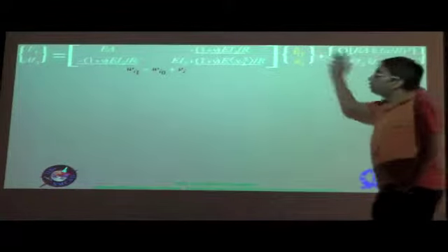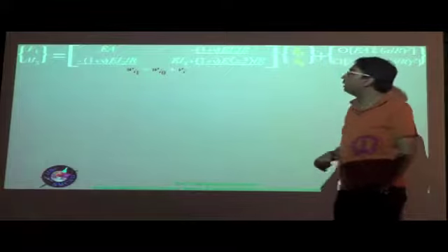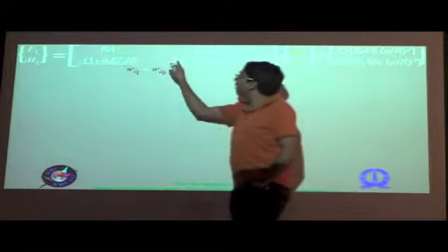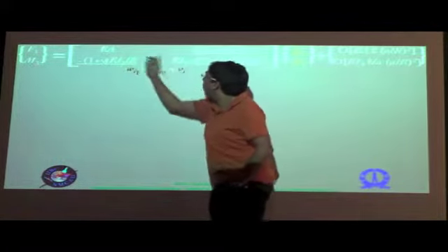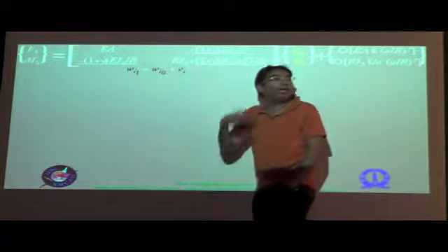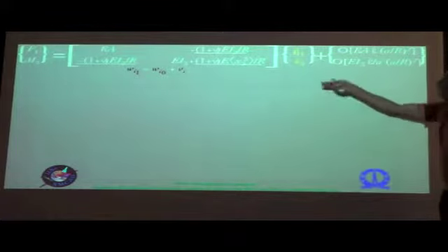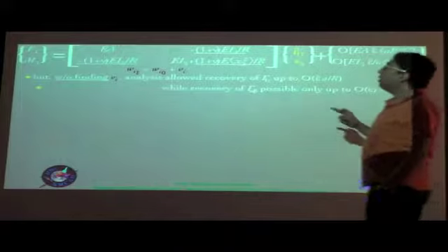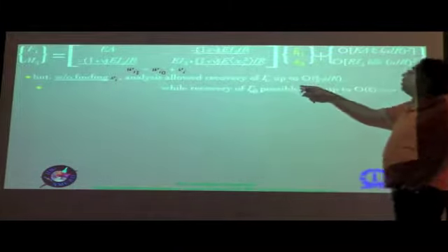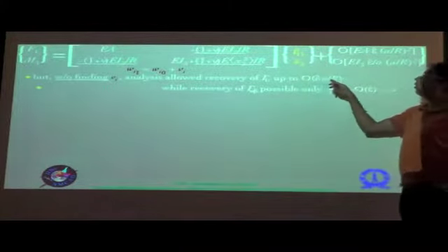So this is of course the constitutive law that we got in the previous example, the isotropic example, and we said that the non-underlined terms were the zeroth order approximation, the underlined terms were the additions that we got with the first order approximation. And of course, if you go to higher order approximation, the next correction, for example, would involve an A by R squared correction in both the axial force stress resultant as well as the bending moment stress resultant. But without finding VI, the analysis allowed the recovery of gamma 1i already up to order of epsilon hat A by R,